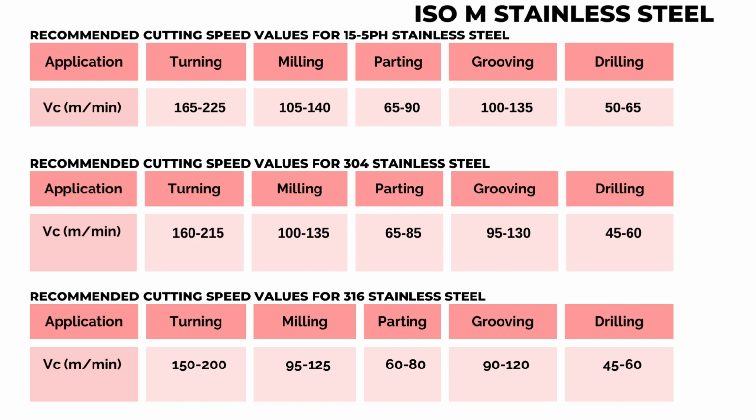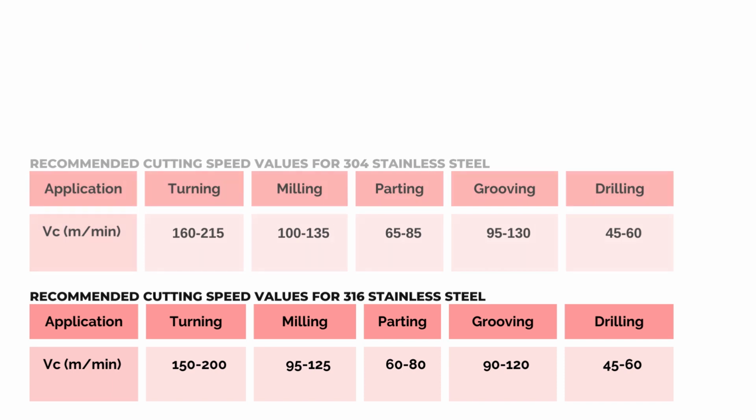For example, stainless steel 304 is an austenitic stainless steel alloy with 19% chromium and 9% nickel. It is a simple chromium-nickel stainless with 0.1% carbon that exhibits excellent resistance to atmospheric corrosion but is not suitable for harsh environments. It is relatively easy to machine, compared with other austenitic alloys, with a machinability rating of 43%.